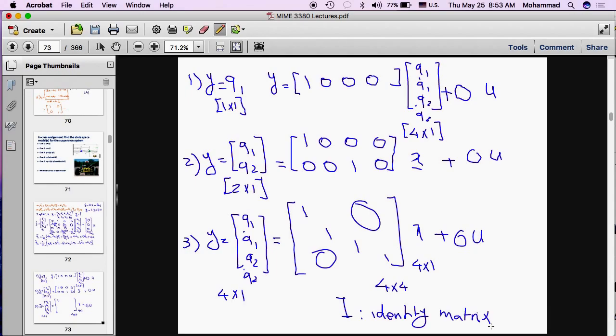So we looked at three possibilities, but there are a number of other possibilities. But you get the idea. No matter what possibility, the first portion of the state space model doesn't change. That's the most powerful feature of the state space model, and it wasn't present in the transfer function. In your transfer function, when you wanted to find another output, you had to redo the whole transfer function. You couldn't, for example, keep the denominator and simply change the numerator.